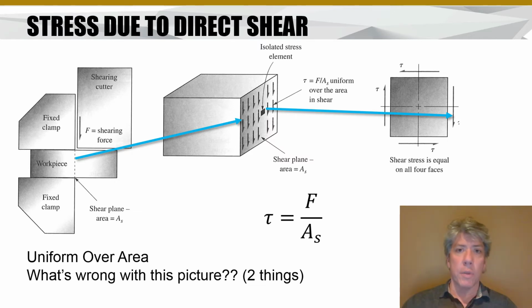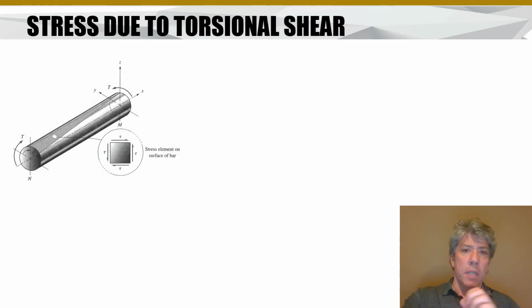In a beam, for example, there's an interplay between the two. The integral of the shear force, which causes shear stress, by the way, also causes a moment, which causes normal stress, right? So there's this relationship between all of them. And there's something else we've done that's kind of arbitrary here. But let's consider the last stress distribution that we've discovered so far. We discovered that when we apply torque and loads to a rod, for example, the rod will deflect, and there will certainly be some shear or shear strain that's generated, and also shear stress.